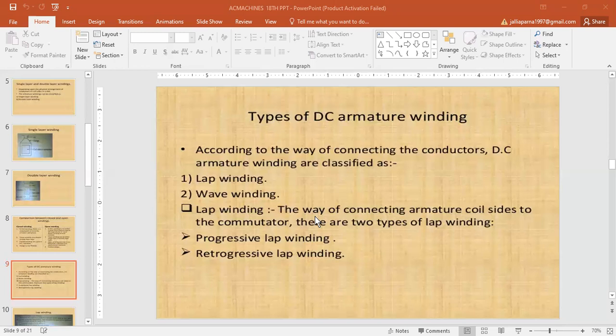Degree of re-entrancy of an armature winding. A winding is said to be singly re-entrant if, on tracing through it once, all armature conductors are included on returning to the starting point. It is doubly re-entrant if only half of the conductors are included in tracing through the winding once, and so on.